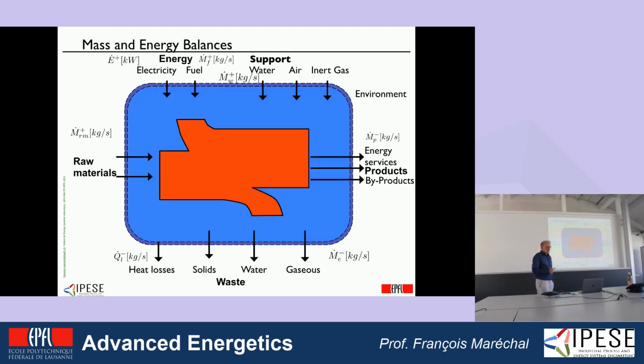Okay. And for doing this, then you will always apply mass and energy balances. Okay. The advantage of writing mass and energy balances means that what is entering the system is always leaving the system. Okay, the only case where this is not true is in nuclear power plants, where they transform a little bit of mass into energy, right? But in all the processes that you will be facing, the mass balance is conserved and the energy is conserved. Okay, and it's very important.